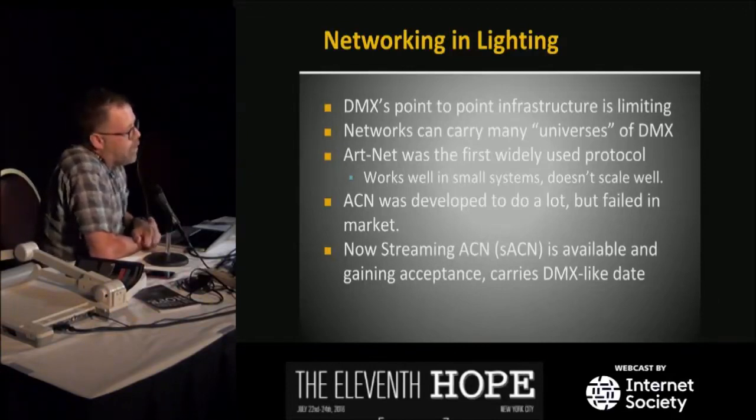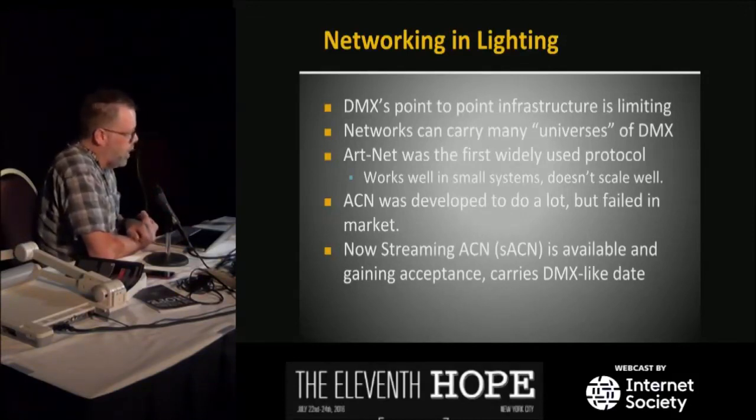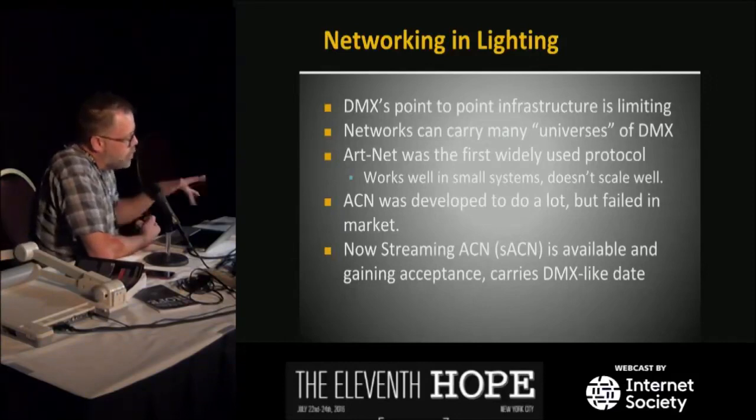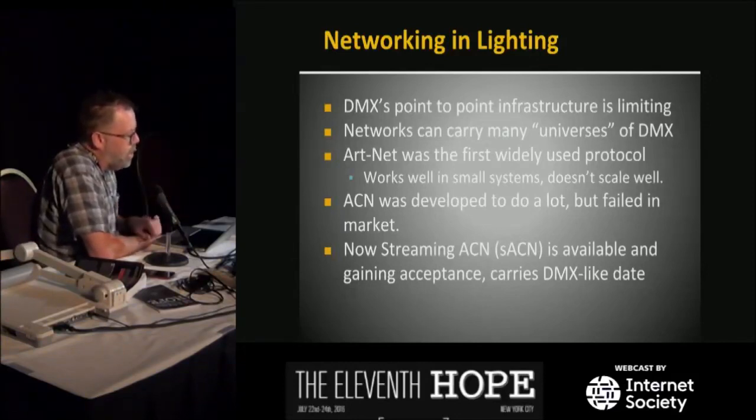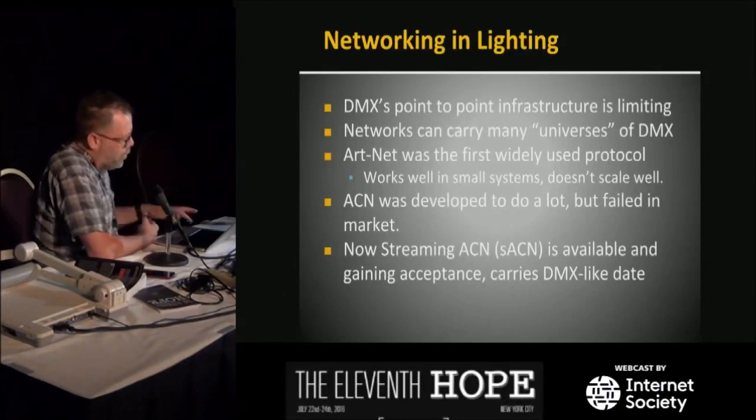So that's now our alternative to ArtNet, and that one is a very modern network-focused protocol that deals with all the issues, multicast, all these other things that we have issues with in modern networks. So those two, streaming ACN and ArtNet, are the two most widely used lighting control protocols in the market right now for networks. I would prefer streaming ACN myself, but they both work.